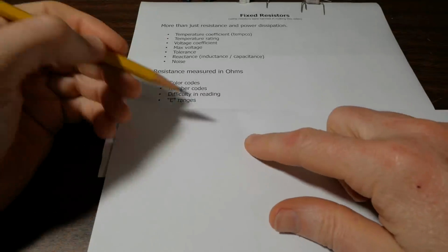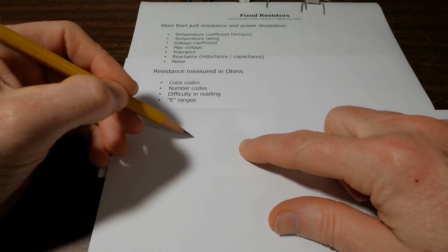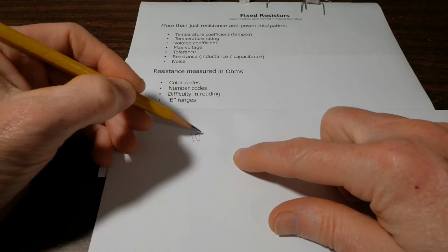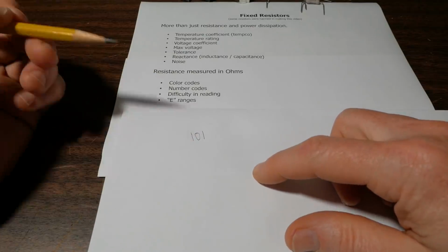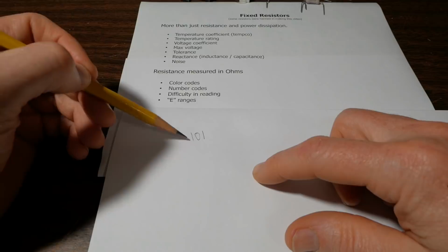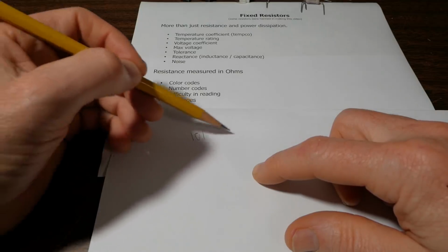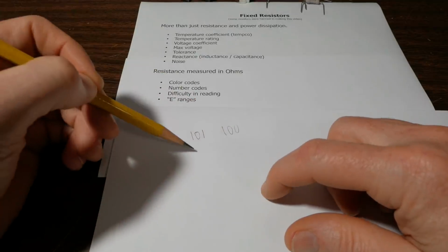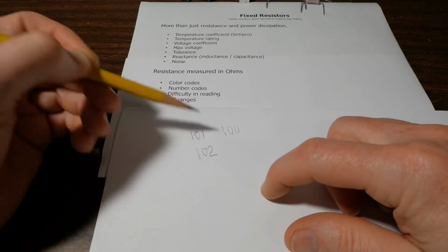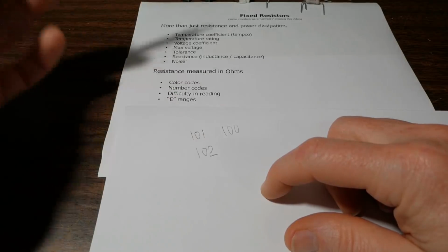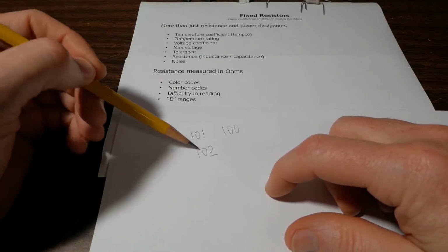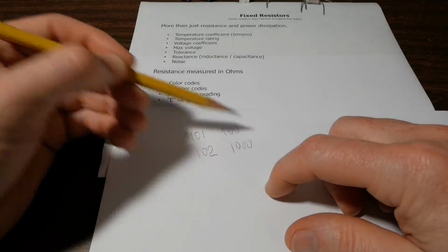Now on surface mount resistors, they don't have the coloring codes, they have a number. So you have to be careful because those can get you sometimes. If you see, like on a little surface mount resistor, 101, that means it's a 100 ohm. So it's 10, and this tells you to put another 0, so it's 100. And if it's 102, it's using the same multiplier system that we just looked at. Of course, this means 1000.